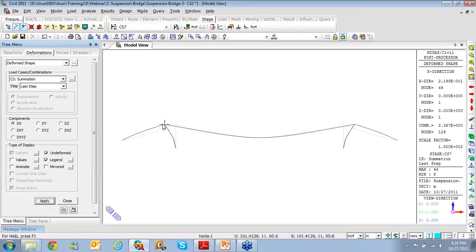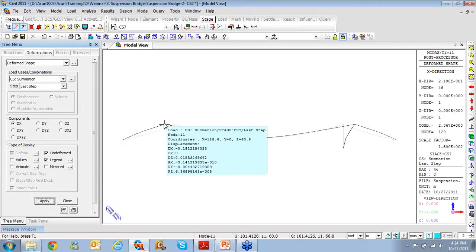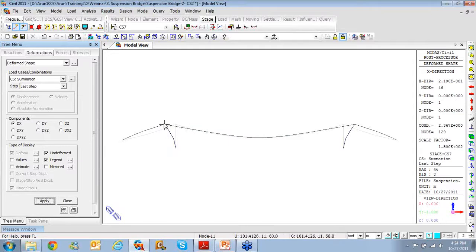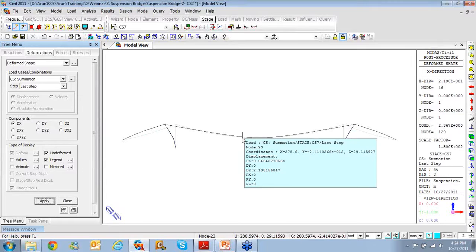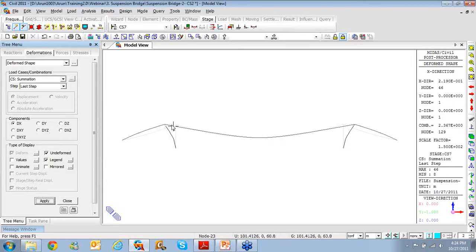So you need to apply a horizontal camber equal to this value as given by the program by pulling them using some additional ropes or cables from behind. And when the structure starts forming from the center towards the outer ends, the pylon will become vertical because the length of the cable is fixed and there is no slipping occurring on top.